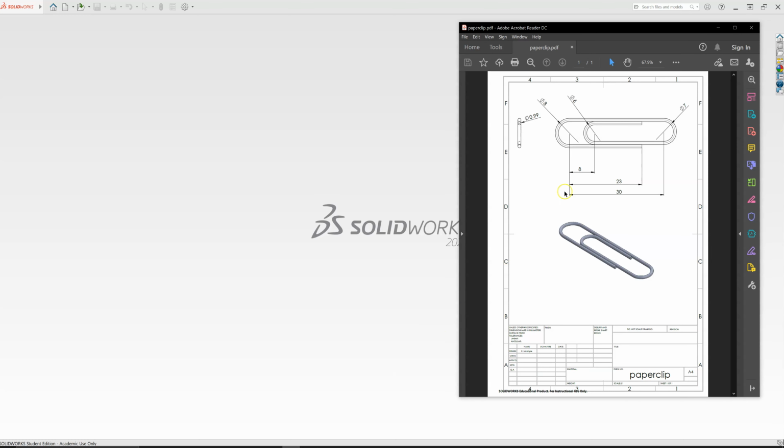In this video I'm going to be looking at the next exercise that we'll be doing in class, this exercise here, modeling a paperclip. So this is hopefully a fairly short and simple exercise really to demonstrate the sweep function, or the sweep feature within Solidworks. Essentially what we're going to do is create a two-dimensional sketch, and we're going to use a sweep command, which is similar to the extrude, but it'll extrude a cross section along a curved path that we'll define by a 2D sketch.